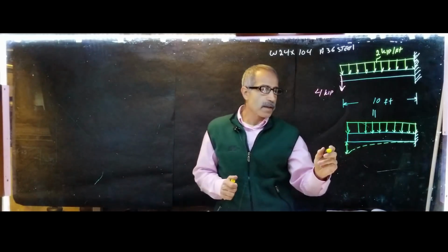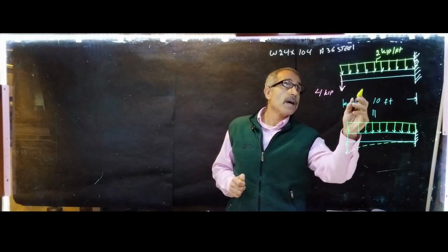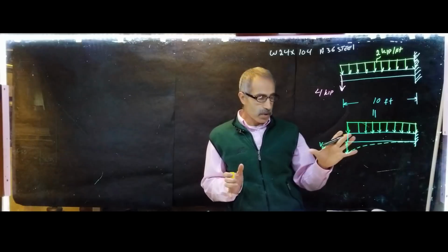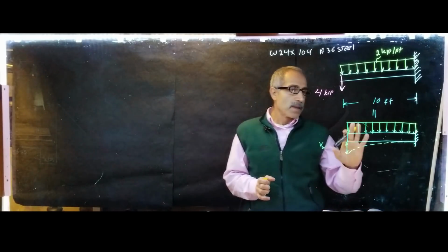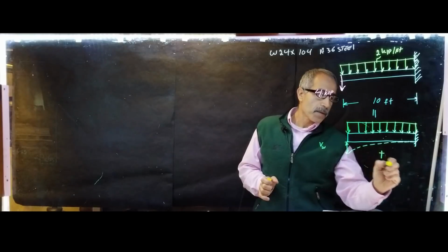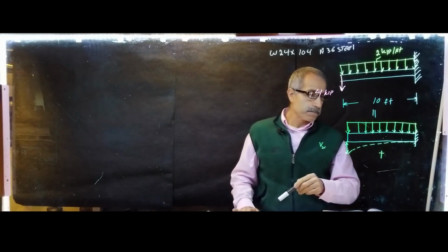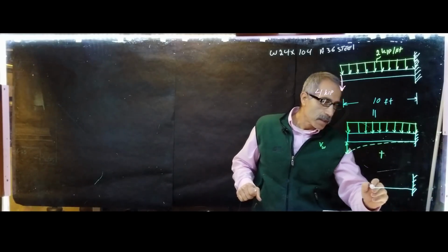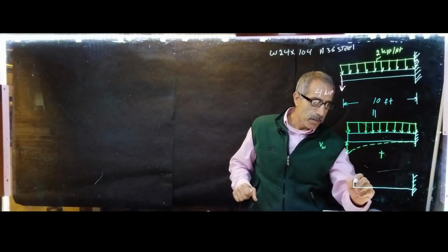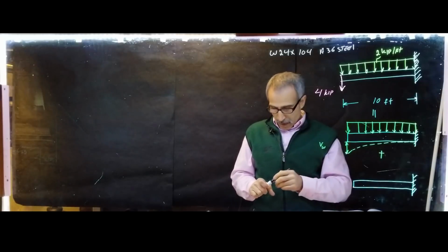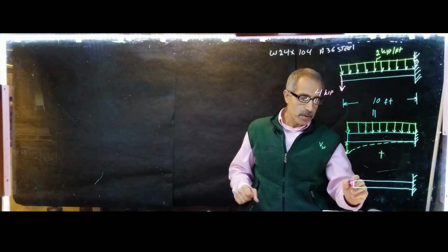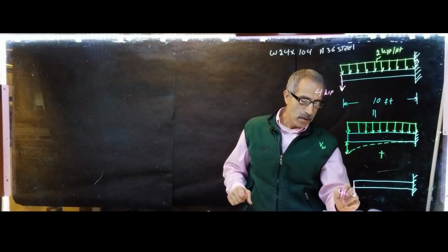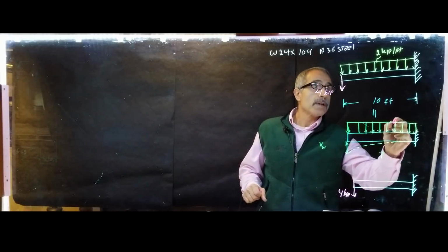Let's call that V of W, and we're going to calculate that by superposition. We're going to go ahead and look at the back of the book. Then that's equal to that plus, don't forget this, same beam, this time only using a concentrated load, which was right here, and this was 4 kips, and this is here 2 kips per foot.